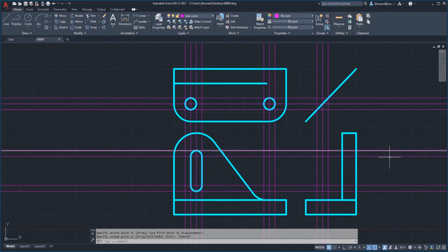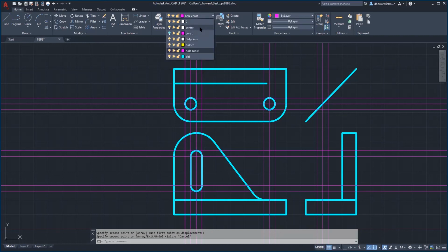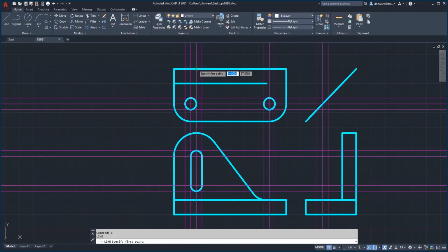Okay, how about we address the slot first? So the slot is visible in the front view. Let's drop it in the top view here. I'll go to my center line layer and show it in the top view. So there is its center line, and I'm not going to bring it across like that.